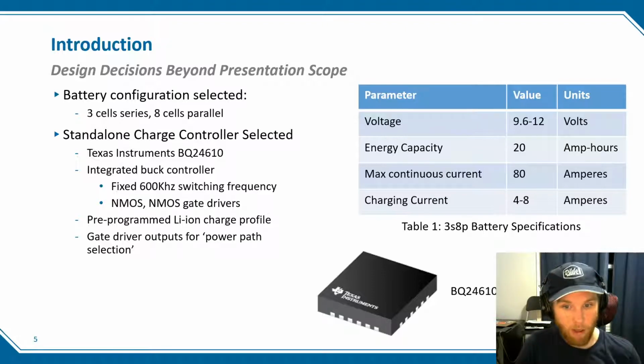All that we really need to know about it is that it's a fixed 600 kilohertz switching frequency, and it has two NMOS gate drivers, one for the low side, one for the high side. It's also bootstrapped, and that also means that it's a synchronous buck converter. It also has a pre-programmed lithium-ion charge profile, so we don't need to worry about doing any lookup tables or anything in an analog or digital control system. And finally, there are gate driver outputs for power path selection. That just comes later in the simulation.